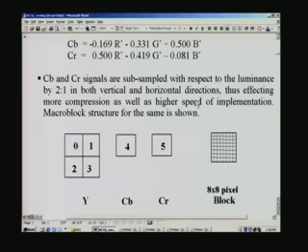And if you do that, in order to process, say this is what is called a macroblock. It consists of 4 blocks. It is only for convenience sake that we divide it as a macroblock, and the standard demands this, and so each one is a block. And what is a block? A block is nothing but a collection of 64 pixels arranged as 8 pixels by 8 pixels, and we will be looking at what a pixel is with respect to the actual image we saw before.